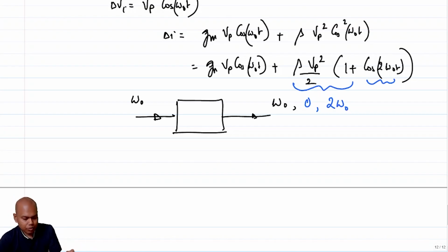In an RF system, note that an LNA is followed by a mixer, right? And if you recall one of the earlier lectures where we were talking about architectures, a mixer does not only contain an ideal sinusoid, it also contains harmonics of the sinusoid. If the mixer is operating at ωLO, it will also contain terms at 2ωLO, 3ωLO, and so on, right?